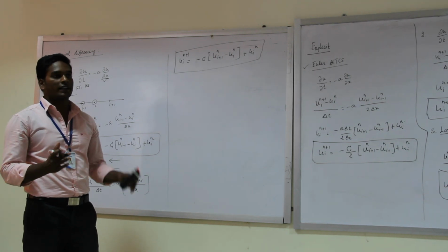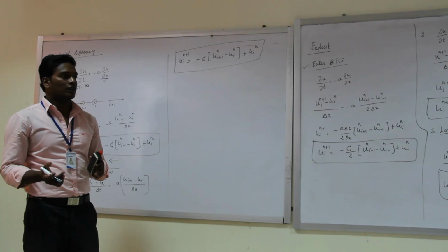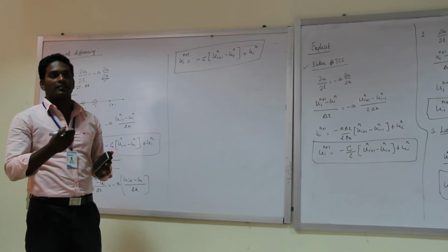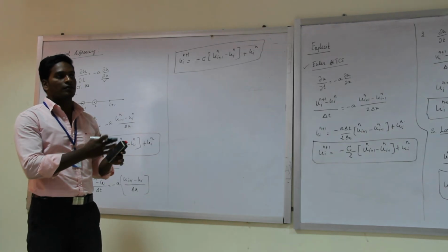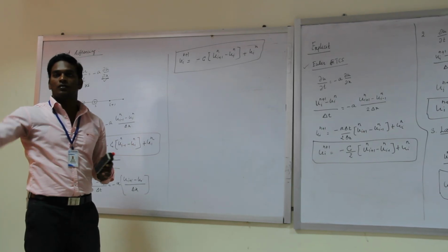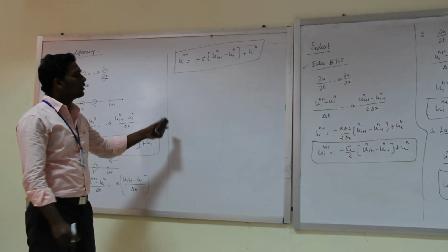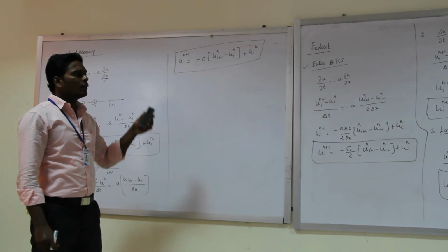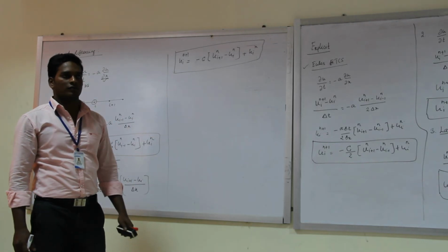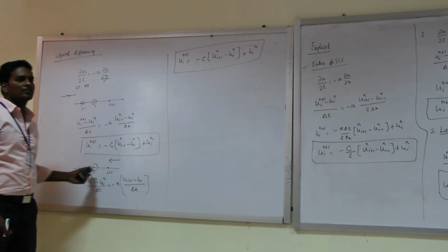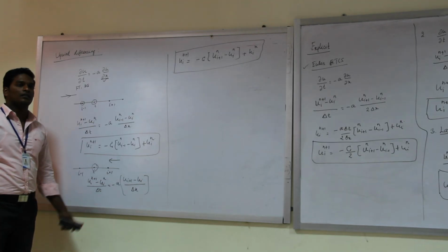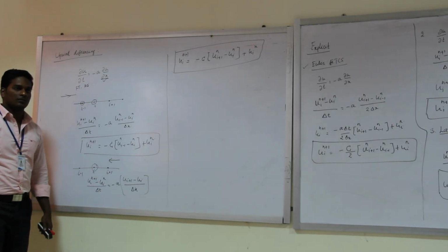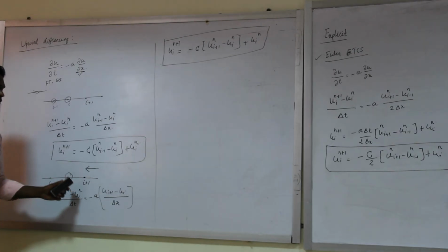So it's working under a shaded region. So you should consider where the disturbance is from, where the disturbance takes place. So with respect to the disturbance and propagation, you have to match your solution. Okay, that's why for so many hyperbolic problems, we would choose and prefer the upwind differencing scheme. Which direction the disturbance is propagated in is preferable, and common sense also tells us it's a good guess. Okay, you consider this where the disturbance node is, it's a good guess.